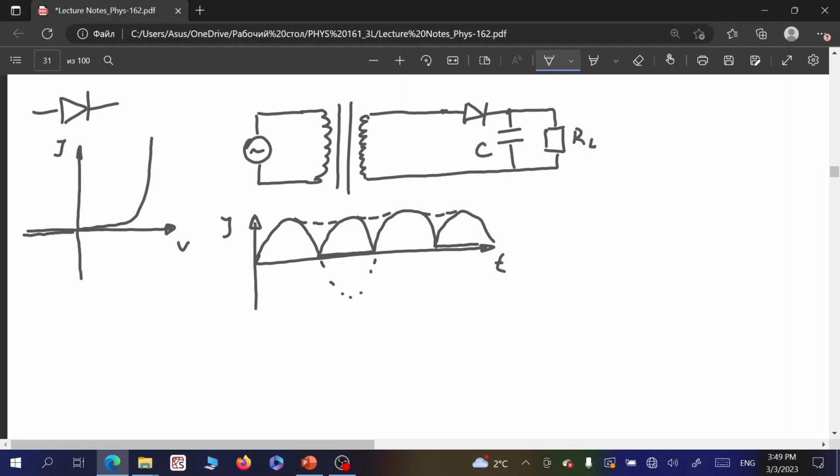So, summarizing, we considered electric power dissipated in AC electric circuits. We figured out that, first of all, only active resistance defines how much power is dissipated, because reactive resistances, capacitive and inductive, during half of the period accumulate energy from AC power supply in form of electric and magnetic fields energy, and during the other half of the period just provide it back to the electric power.